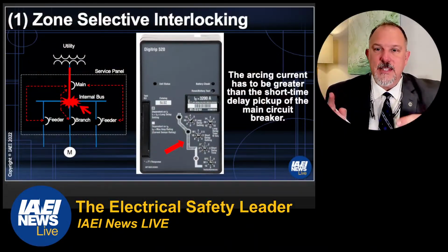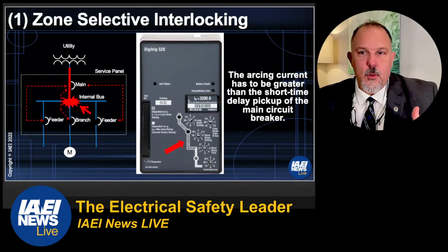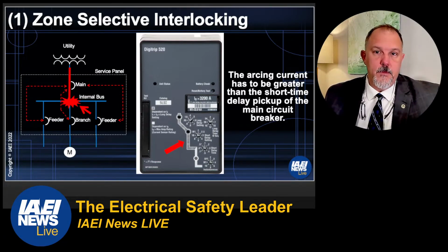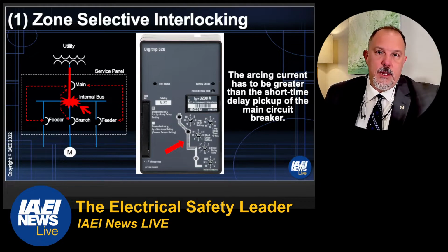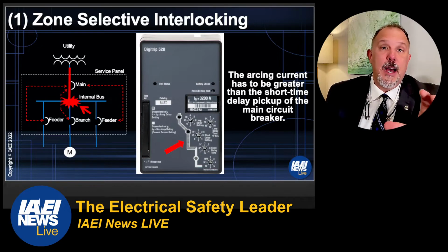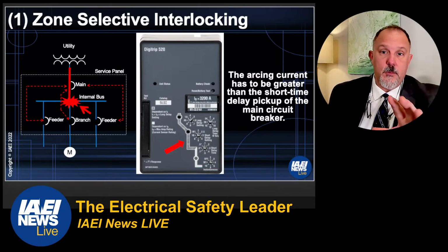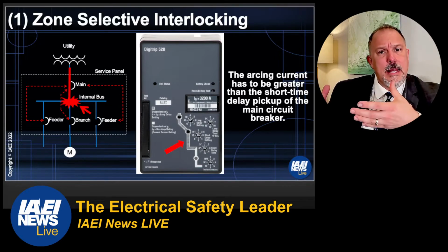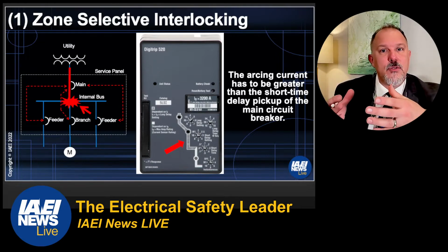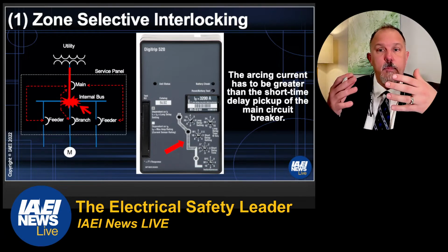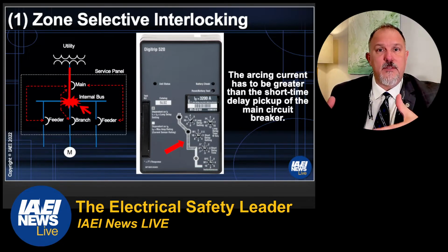So you take a device like this. This is a trip unit for, say, a power circuit breaker or an insulated case circuit breaker. Now, I'm showing a trip unit like this, which would be on a power breaker or an insulated case, but I could have a trip unit that doesn't fit this form factor, but is smaller and fits into a molded case circuit breaker. So now I have an electronic brain inside of a molded case circuit breaker.